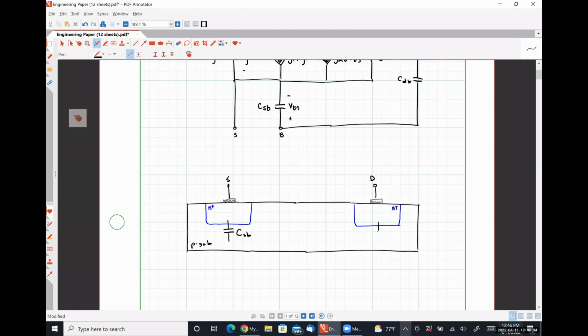We have N-type material right next to P-type material, so we have a PN junction, which will in turn have some capacitance due to the charge stored in the depletion region. This junction is also going to be reverse biased effectively all of the time. So we should see a junction capacitance based relationship here.